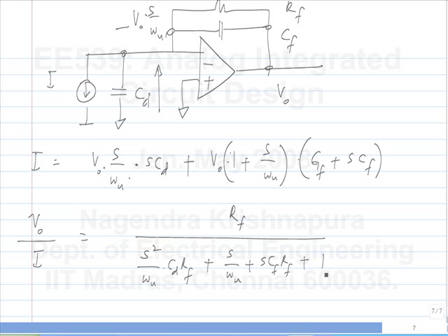The loop gain had a zero in it, right? Yeah. So looking at the Bode plot also you can decide that, well, you could have a pole and a zero very close to each other. You can't really say. Okay. So anyway, think about it. Why doesn't it show up in the closed loop?